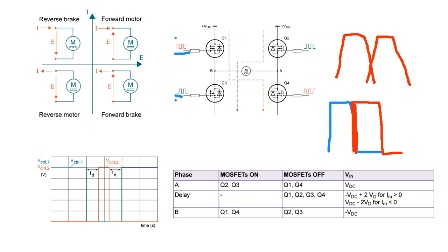We can apply a delay at that time, like this one. You can see here, falling, and the rising time. We can add dead time there. For example, at 10 kilohertz switching frequency, it means a minimum of 3.6 microseconds delay, for example.